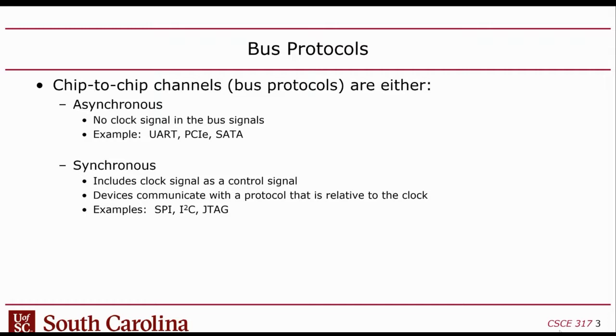Now, PCI Express and SATA are also asynchronous, believe it or not. As advanced as they are, there's no clock in there. That's because they're so fast, it's not practical to put a clock. The way they work is you encode the channel. You use 8b/10b encoding, where you take every 8 bits and turn it into 10 bits. Or they even have ones now on FPGAs that I use where 64 bits gets encoded into 66 bits.